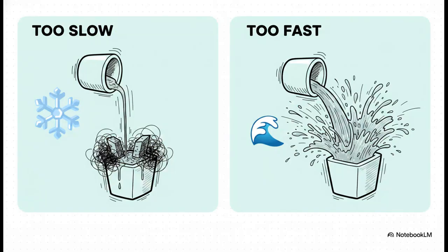And then we have the volumetric pouring rate. This right here is the ultimate Goldilocks pacing challenge. If you pour that molten metal too slowly, you lose your superheat way too fast. The metal will literally chill and freeze prematurely, blocking up the gating system before your cavity is even full. But on the flip side, if your pouring rate is too fast and aggressive, you introduce severe turbulence into the system. It really has to be just right.